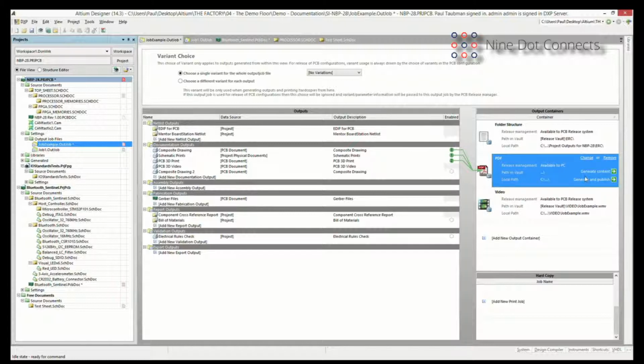The other option that they've got over here is this thing called Generate and Publish, and that's really important as well. And I'm going to show you this because sometimes you don't want to necessarily keep this local to your directory. Sometimes you want to make this available to people on the outside, and maybe you guys have an iCloud, some location, right, someplace on the cloud that you want to put these things. And we can do that by clicking on Manage Publishing, and Altium can link to those things through its preferences.